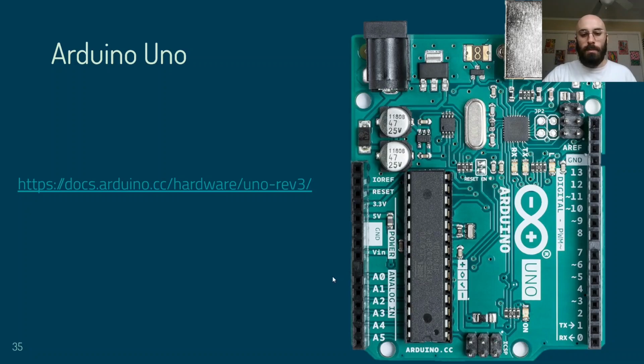But now we have these. These are analog in. I talked a little bit about digital, which is representing information as a stream of zeros and ones. And then we talked about analog music, which would be something recorded to a tape or a vinyl record. That is representing music in an analog way, meaning that there's an infinite range of values that we can use to store information. So these are labeled as analog inputs because they allow us to read in information with a little bit more granularity than we do with our digital pins.